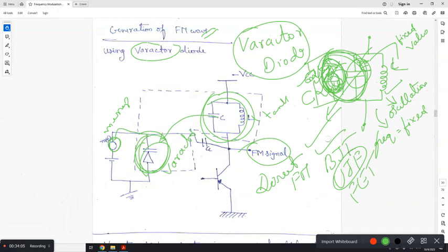See, when you studied FET, field effect transistor, there is some internal capacitance. How many of you know it exhibits some capacitance? There is a relation you get, transconductance, which will vary according to the input voltage. You have an active device whose capacitance between its gate and one more terminal will vary according to the input voltage. If you make that circuit parallel to the tank circuit, the applied voltage will vary the capacitance, and capacitance will vary the frequency of oscillation. Ultimately, the tank circuit is very important, that's all.